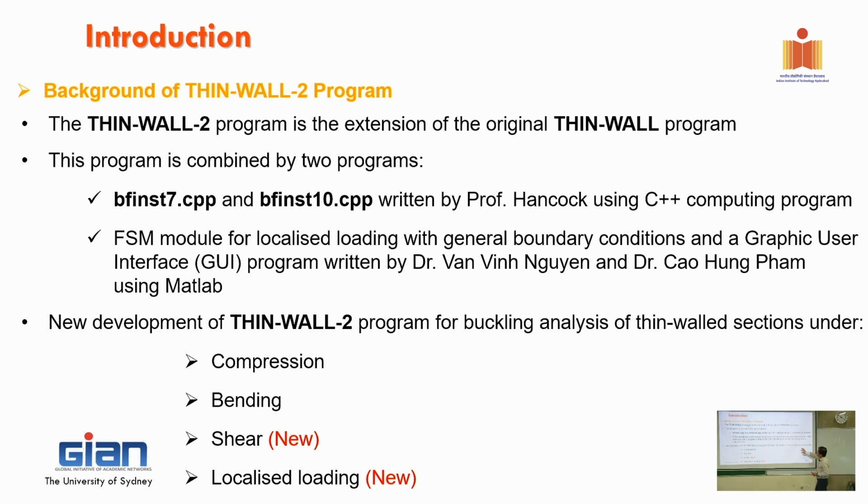So what's new in THIN-WALL-2 is this one. We include shear, and we include localized loading, and then you can design for that. Those are new and different from the program CUFSM. Are you aware of that program, right? That program is very similar to THIN-WALL, the previous one. But now THIN-WALL-2 has a little bit more than what they did: we can design for shear, and we can design for localized loading.